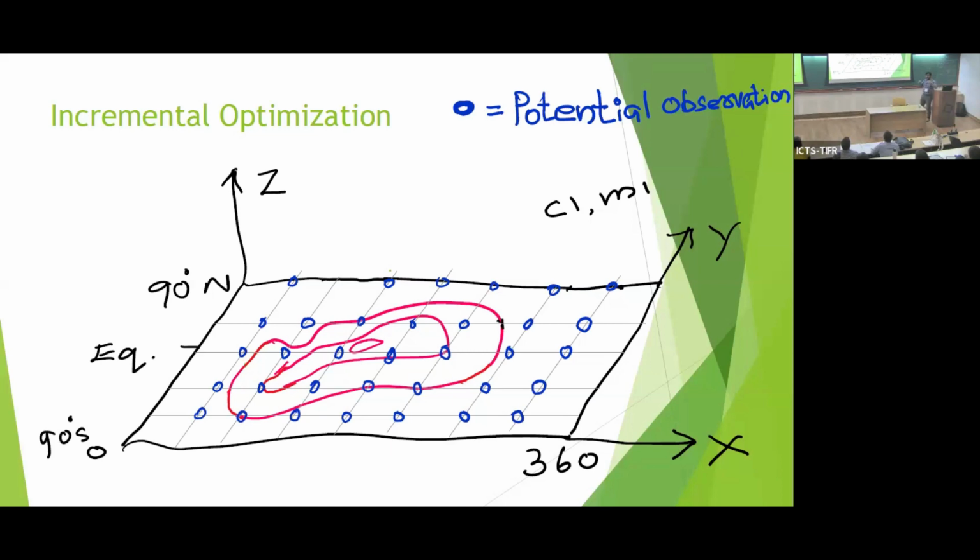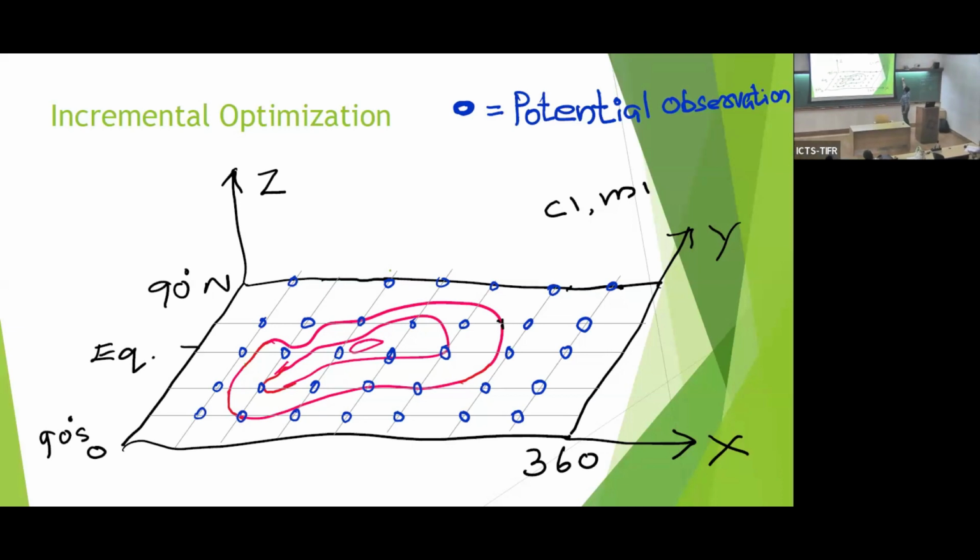So, you will get an uncertainty reduction, say, a number, mostly between 1 to 100, right. So, one station gives 25% uncertainty reduction, the next station independently, okay, you are not combining them, gave 13%, one station gave 0.2%, another station gave 36%. So, as many uncertainty reduction values as you can calculate for individual stations in your model, sort them in descending order. So, you will find this station is my best station if at all I have only one station. Don't lose it, you keep it.